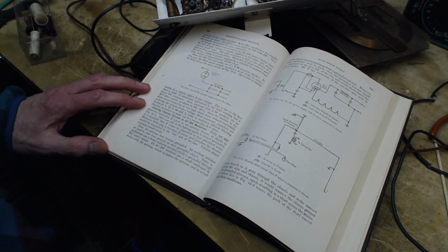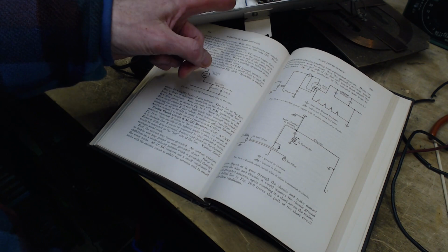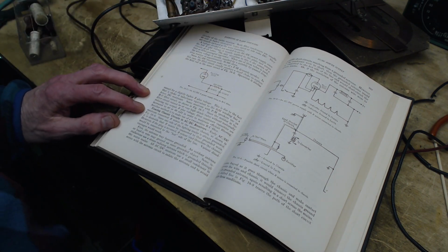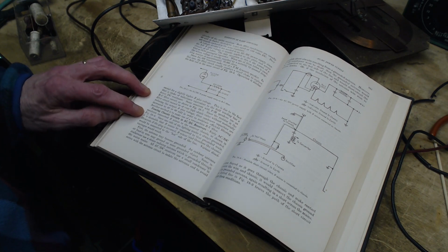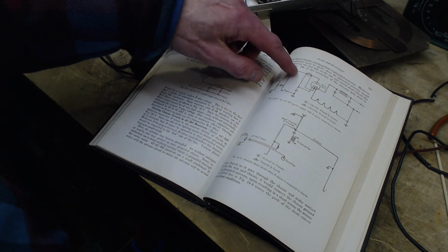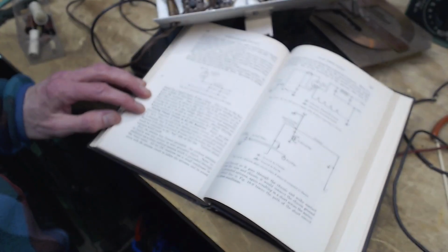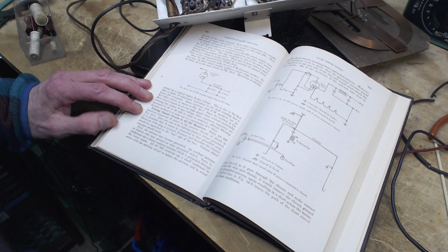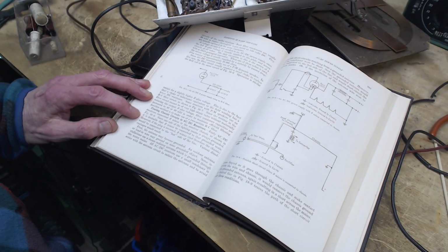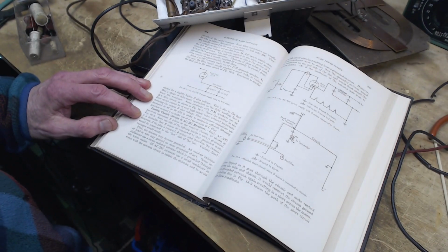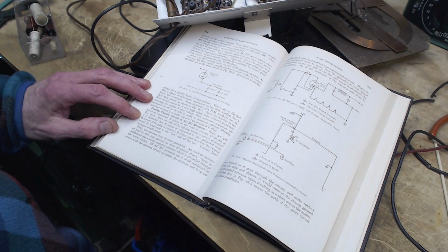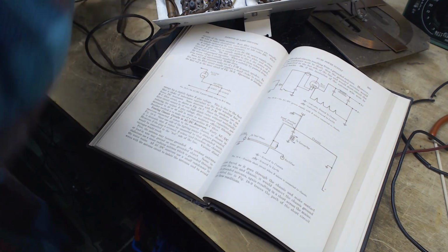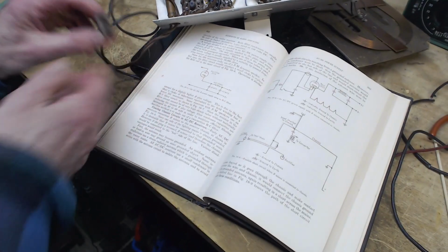Floating chassis circuits and AC/DC receivers. This is an AC/DC receiver. Early AC/DC receivers connected B- to the receiver chassis, as shown in figure 818. I guess this would be here. Since one side of the lighting mains, this is a British guy, of course, talking, the lighting mains is always grounded, it is desirable that B- be connected to that grounded main. However, if the plug is reversed, they're talking about the unpolarized plug.